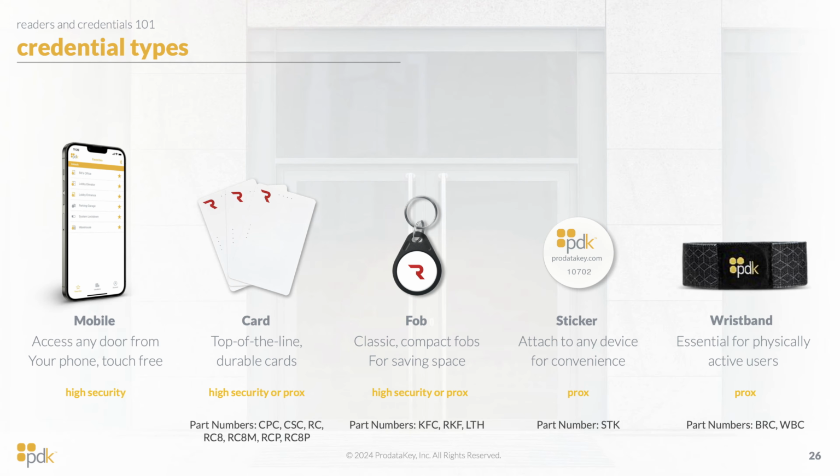The card is capable of coming in a couple different formats dependent on what you need. So the RC is a typical high security 13.56 megahertz encrypted credential. We have the RC8, and that 8 specifies the memory on board, 8 kilobits of storage on board. We have the RC8M, the RCP, and the RC8P. That P in the RCP and RC8P stands for procs. That means that it has both high security and procs capabilities. And then that M on the RC8M is for a mag stripe, if you have a facility that still uses those.